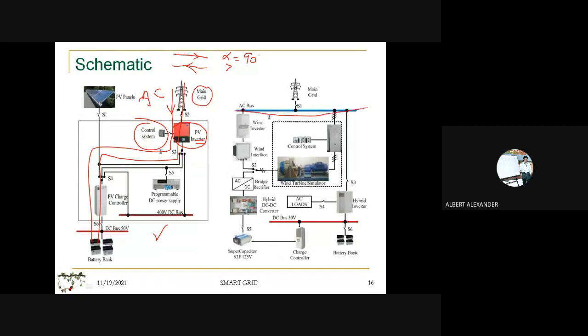Let's assume the wind is generating AC power and we have the AC interface. So I want an AC to DC converter, and I can use either a normal wind turbine or a wind simulator, and then this DC will be stored with the help of a super capacitor, and then it is given to the charge controller, and then it is given to the DC bus.